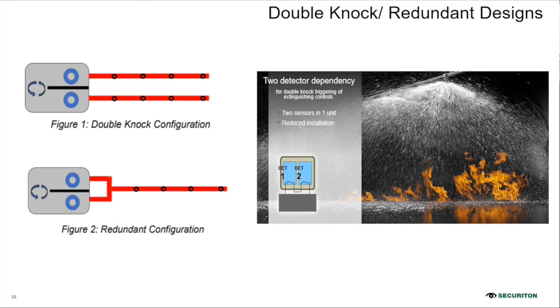Independent detector modules and sampling points, with sampling holes adjacent to each other on both pipes. The advantage is the discharge of the extinguishing system in case of real fire. Both pipes will run in the same area, with one pipe more sensitive and the other pipe less sensitive.